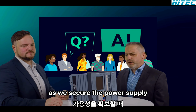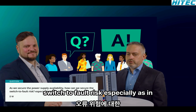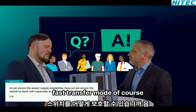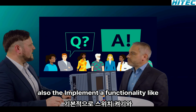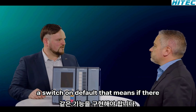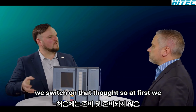As we secure the power supply availability, how can we secure against the switch-to-fault risk, especially in fast transfer mode? Of course, this could be a reason, but we have also implemented a functionality like switch onto fault. That means if there is a fault on the alternative incomer and we switch onto that fault.